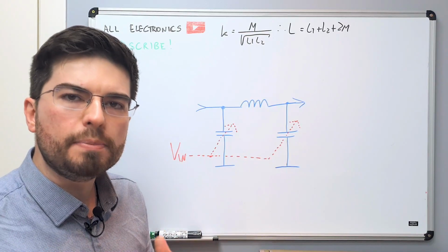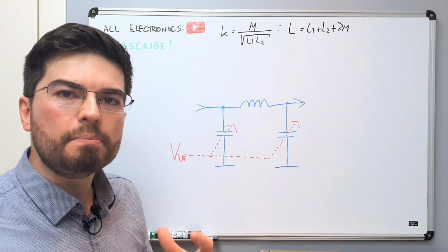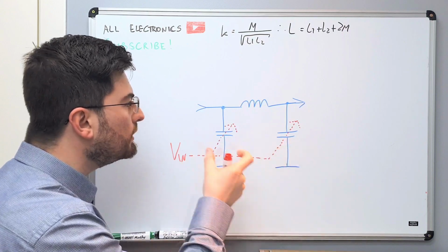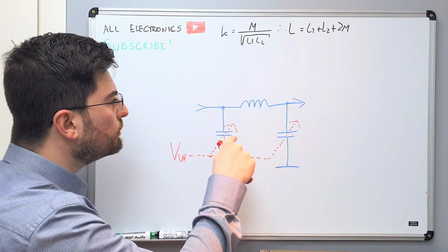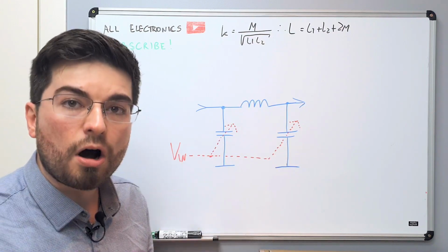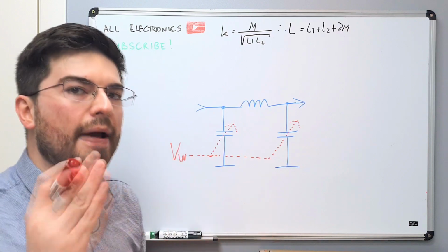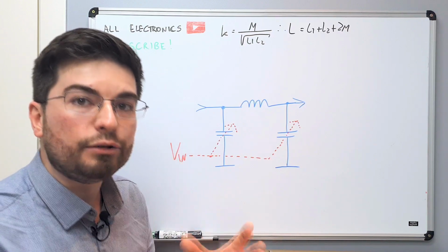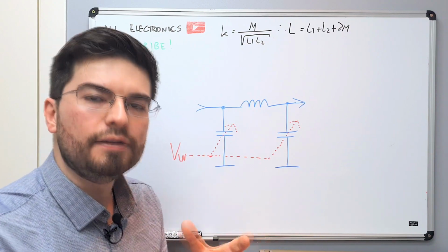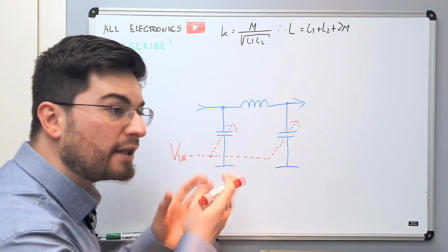So, what is parametric modulation? And of course, how can you use it to make an oscillator work as a frequency divider? Let's see. We create the parametric behavior when we modulate a parameter of the system. In the case of this circuit, we are modulating the capacitances of the oscillator LC tank. We are changing in real time a parameter of the circuit. This is called parametric modulation, and parametric modulation can lead to parametric oscillation, or in this case injection locking, by subproducts in frequency generated by the parametric modulation.